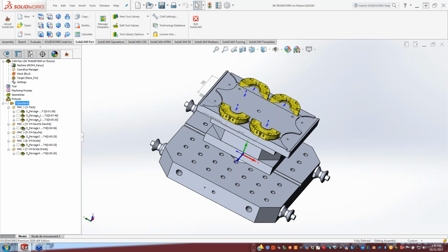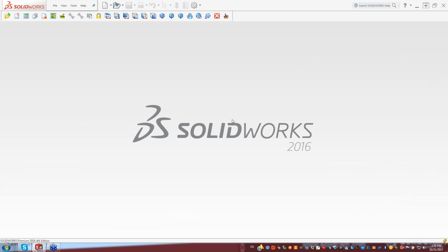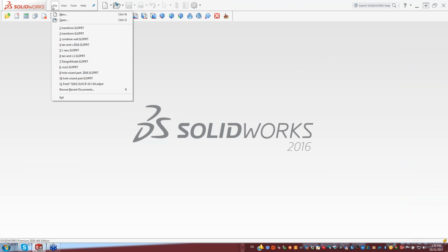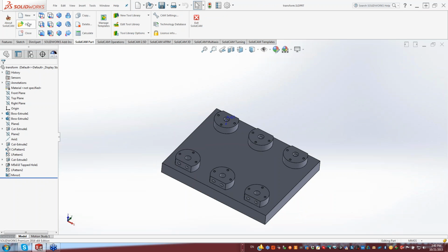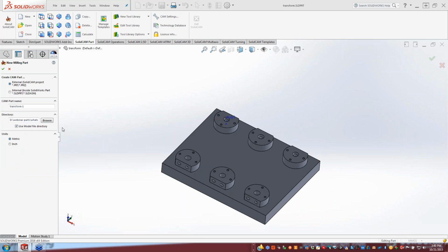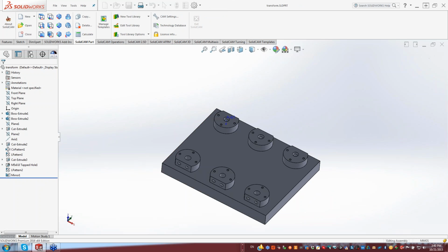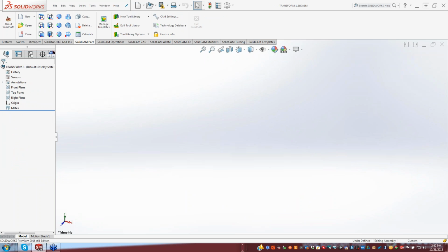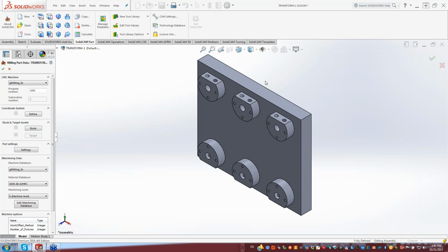Now, as far as our new start of a project goes, let's take a look exactly how that looks. If I were to start, say, a new project, I go New Milling. You'll see that we now have the window in our left-hand SolidWorks tree. Okay, it's not covering over the part anymore. Now, after I accept it, we've created this, and we're going to create our coordinate system.